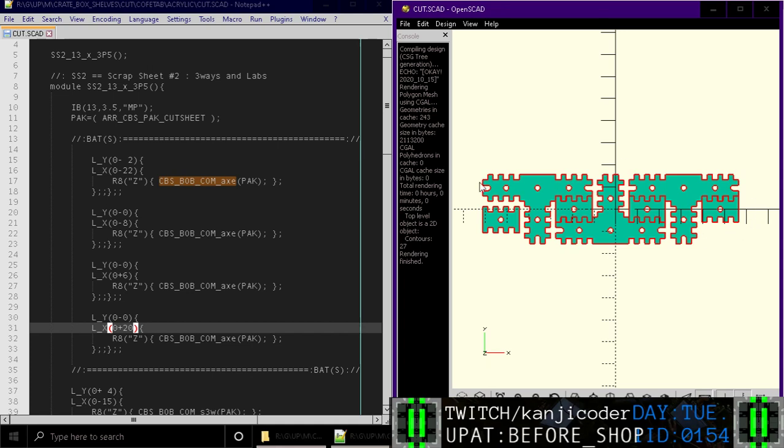So if I have a very strict way of doing this, where the notch in the scrap material is always going to be placed on this side of the laser cutter, in this bottom right corner, and it's not going to be placed up here. The notch in the scrap material is always going to be here. If I'm consistent about that, things are going to go much better for me. So yeah, let's roll with that.